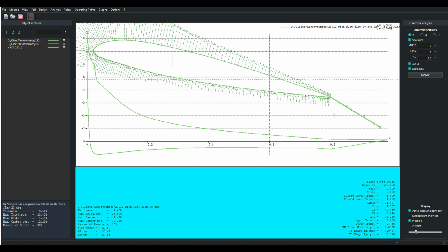that's a big benefit. You have very little inertia left here, and what we've done is we've let the flow finish getting through the adverse pressure gradient and back to almost free stream conditions, and then we turn the corner. Because otherwise we're asking it to get through a nasty adverse pressure gradient and turn the corner. It is just too much to ask, and the flow goes off somewhere else. Here, it's got a better chance of having some energy in it. It has the free stream velocity, and it'll get around that corner and go down the flat plate.